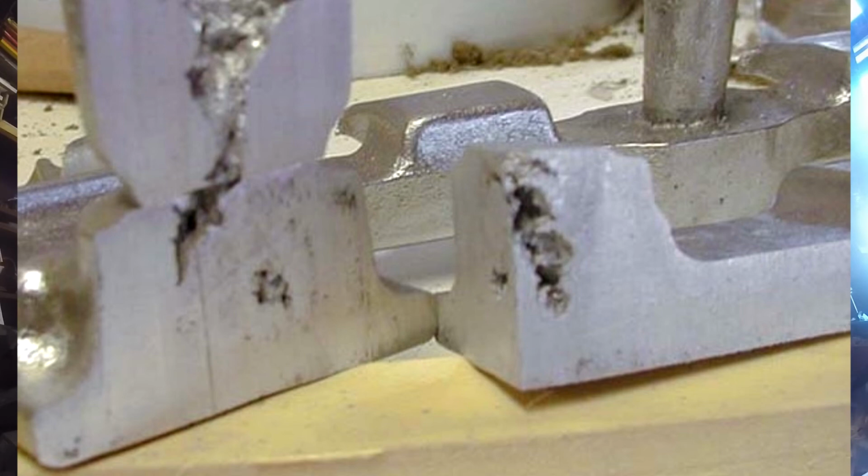Now on the left hand side, it shows where the riser, which apparently was an open riser, was fairly large, except look at the neck where it joins the casting. It's nowhere near the width of the casting, and nowhere near the width of the riser. So apparently that froze up and didn't allow the final solidification of the casting to take place before that froze up.